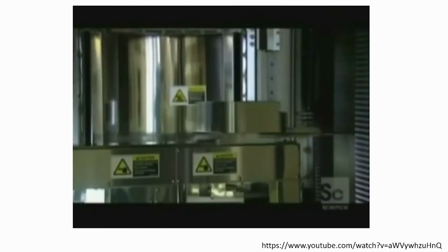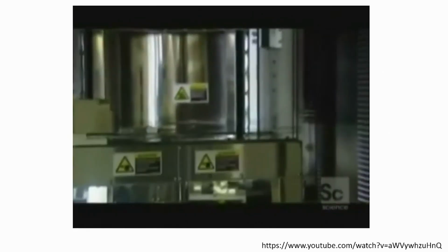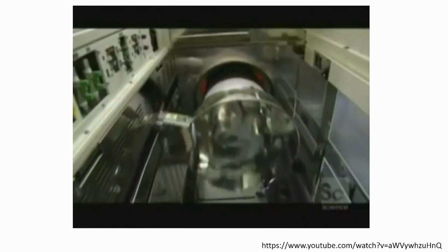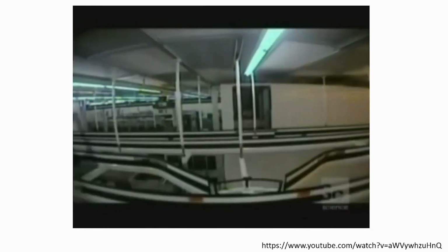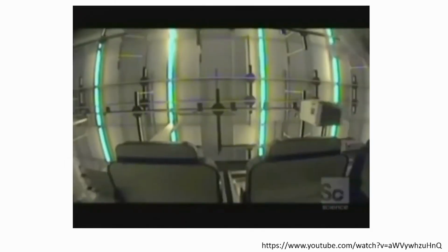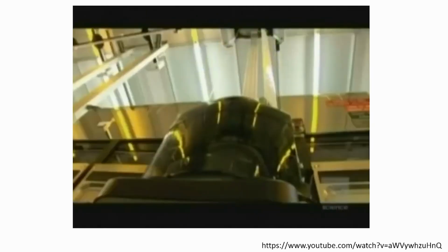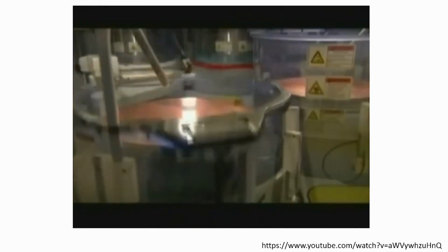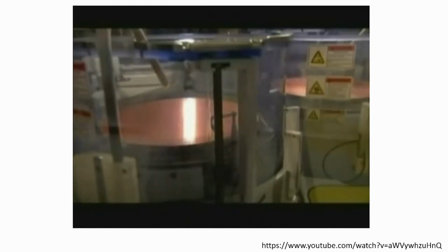But in order to pack all the components onto the wafer, they are built up layer by layer, like floors in a miniature skyscraper. To complete the job, the FOUPs cycle the wafers up to 40 times, repeating the photo etching process for each new layer. Some layers are cooked, some blasted with ionized plasma, some bathed in metals. Each different type of treatment changes the properties for that layer and slowly forms part of the jigsaw making up the chip's design.